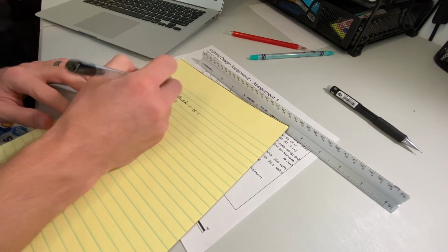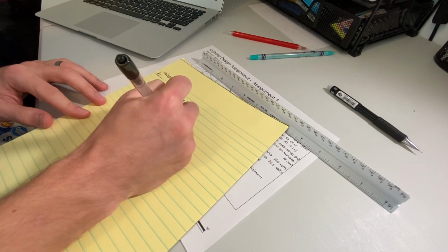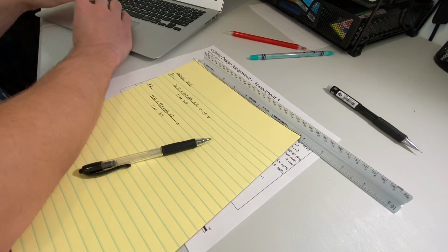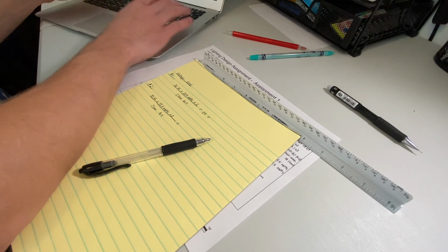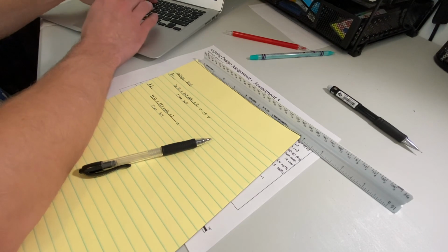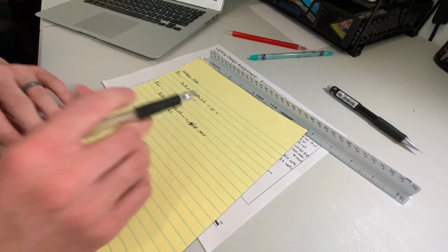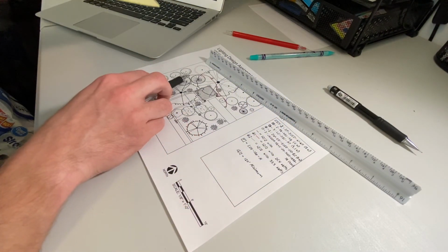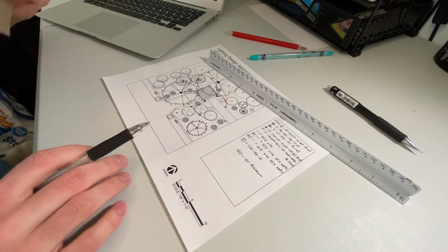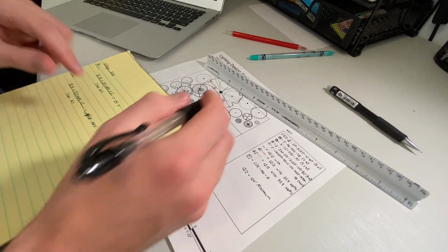Multiply that by 2, and then we're going to divide that by 7500 because it's 12 gauge. So I got 0.40 volts. So at this furthest light, if it's giving off 15 volts, this is only getting 14.6 volts, which is still within the parameter.